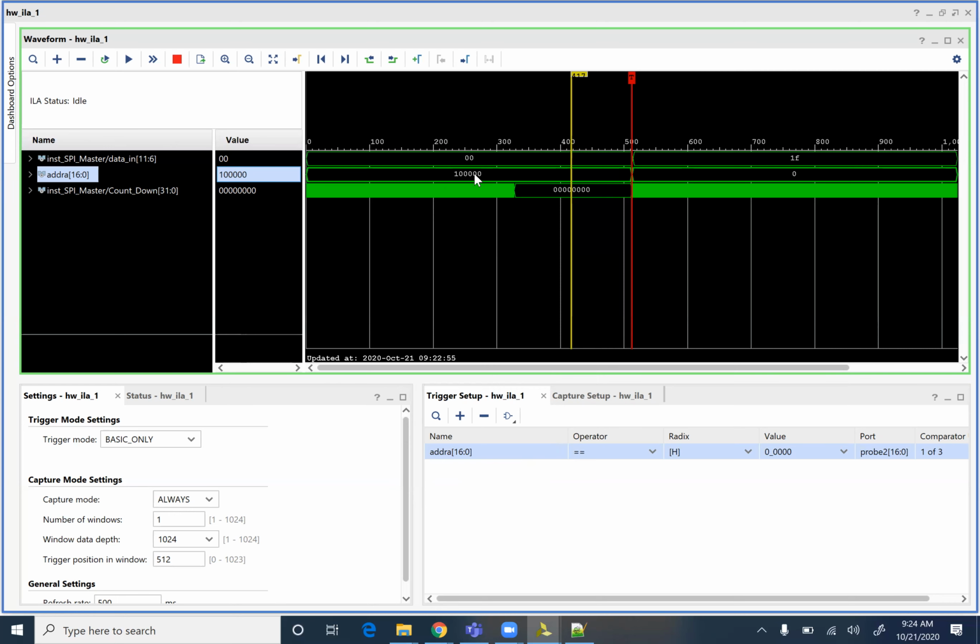So this is showing that my debug, this one is running at 100,000 and then going back to 0. So this is working with the addresses. Or not. It looks actually to me like it's running one address too long. Minor hiccup, probably not even going to be noticed, actually. I don't know how else you would find this out other than using the Debug Core, in fact, because it's such a tiny little blip in the waveform. That was a thing I had where every so often you had a little spike.